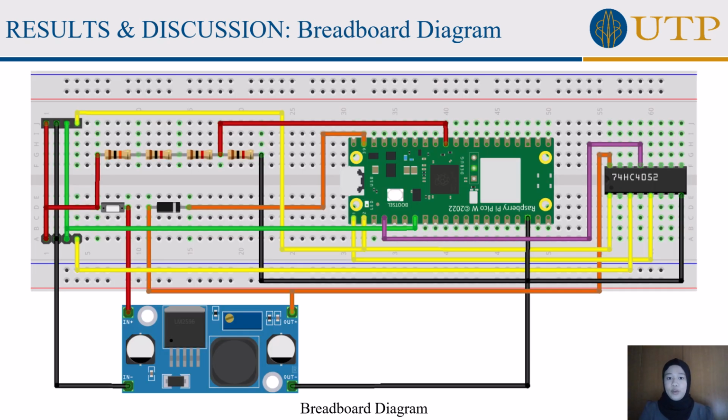Here is the breadboard prototype for an e-scooter range extending add-on circuit that features a Raspberry Pi Pico 2W as the main controller, a multiplexer for signal switching, and a voltage divider for 3.3 volts logic compatibility. The setup includes UART lines for display or motor controller communication, with GPIO pins managing multiplexer control. This testbed enables signal processing, voltage regulation, and switching validation before PCB implementation, allowing for easy debugging and modifications.